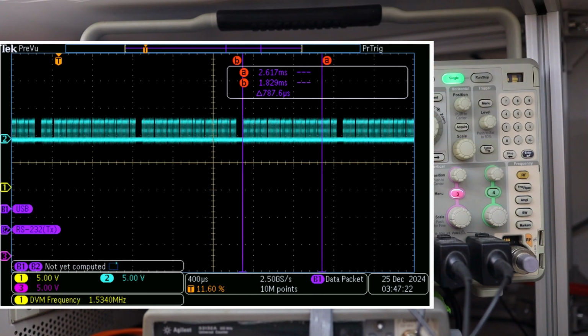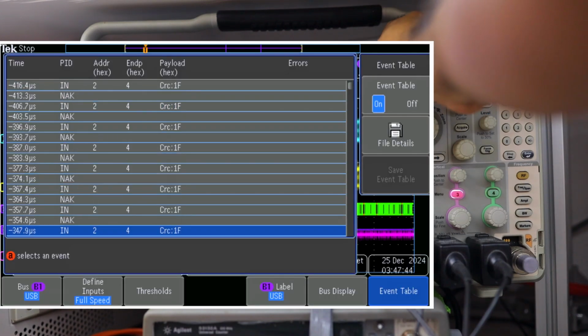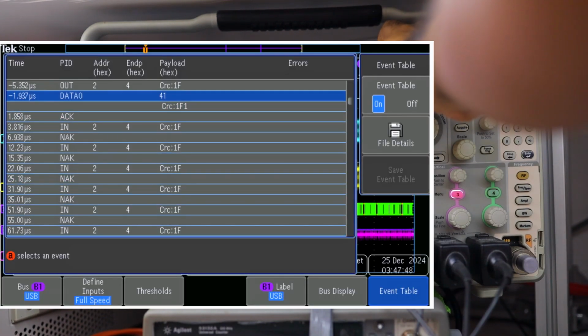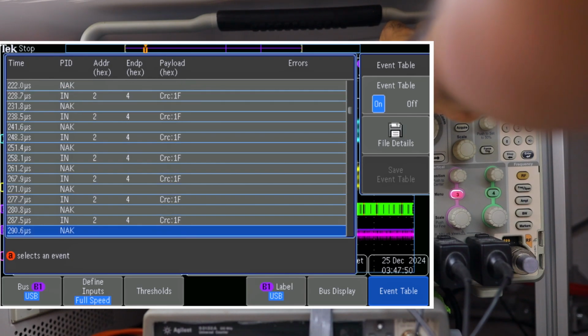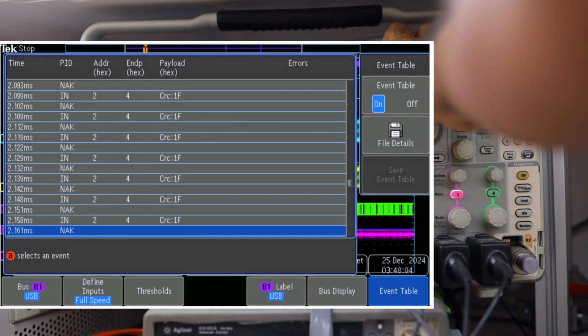We'll do one more single capture. One more transmit A. Event table, same stuff. At 0 point we will see the data with 41 is there, and we need to find out the data going back. This oscilloscope does not have segmented memory, that's why we cannot capture one after another.